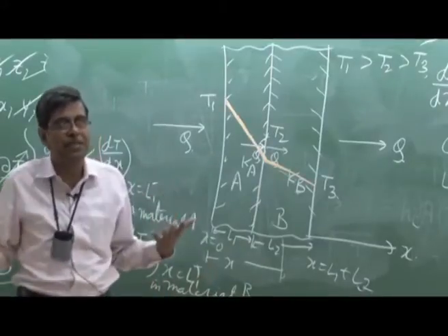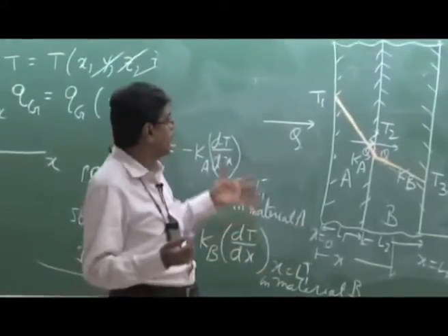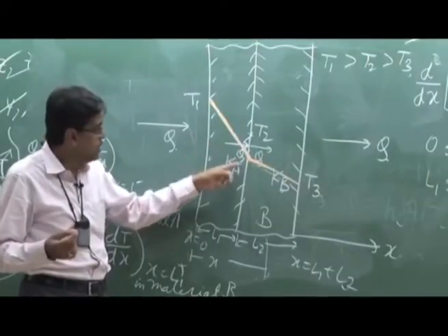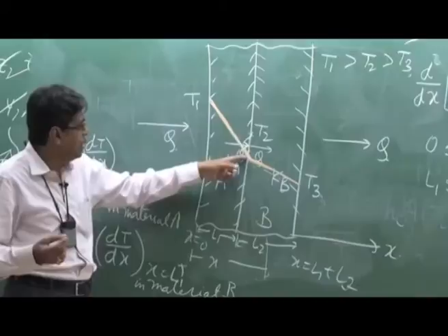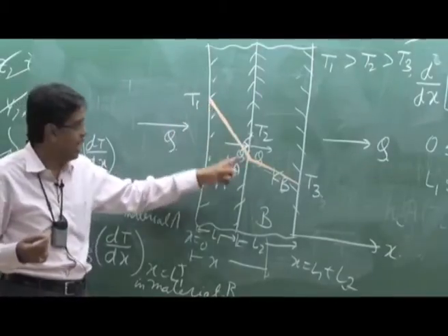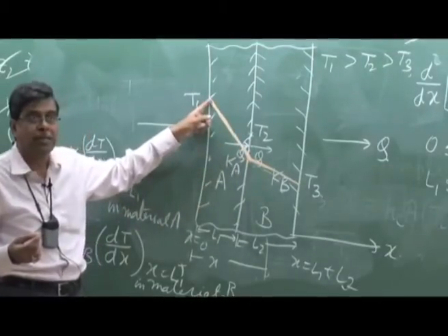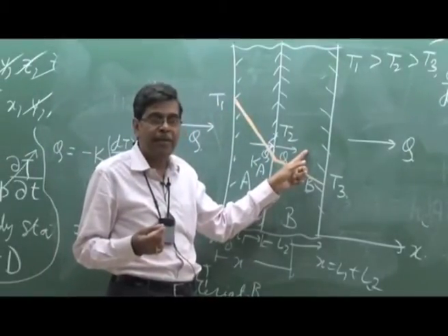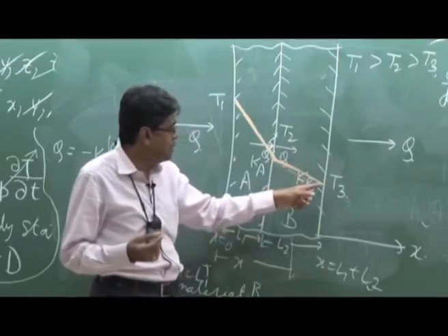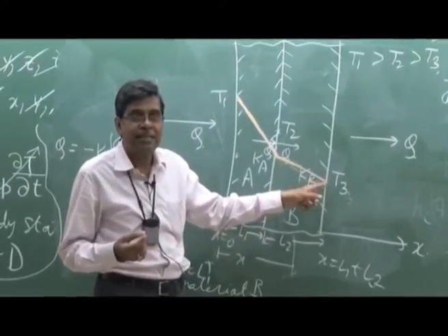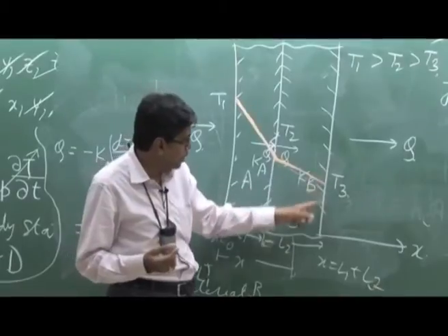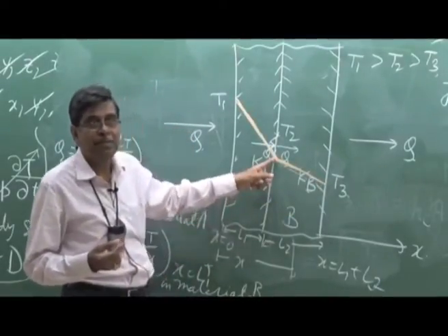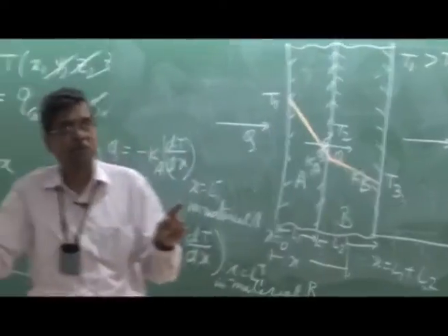And if we apply our physical sense, then also it is true that here, since the thermal conductivity is low, at the end of this plate the temperature is less than this. That means it cannot sense a temperature very close to this. But since the thermal conductivity of this wall is high, the downstream side, this outlet face, has a temperature close to the inlet face. So therefore the temperature profile is flat.